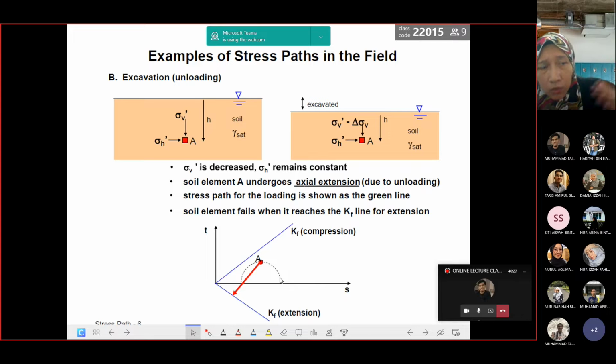of the vertical stress. However, when you relate to the stress path in the opposite situation, in unloading for example, you will see that our effective vertical stress is getting decreased. I mean, if you look in terms of effective depth, H has also decreased. How then do we relate it to the T and S stress path, which represents the failure point? So the stress path is the simplest way to represent the failure of the samples.